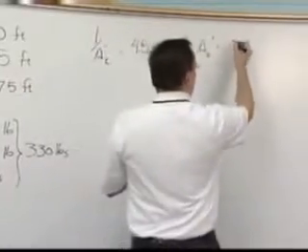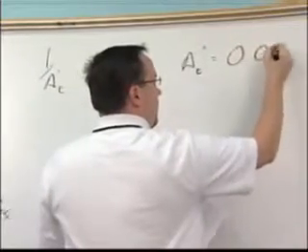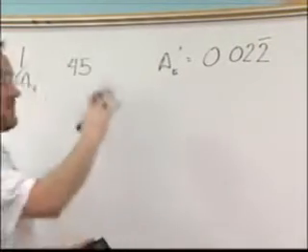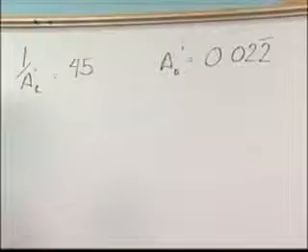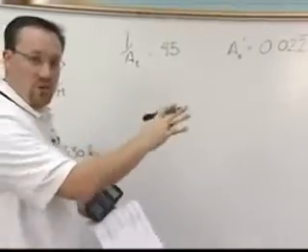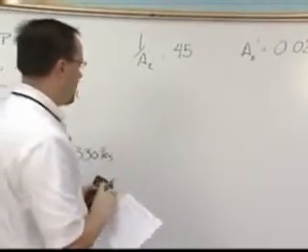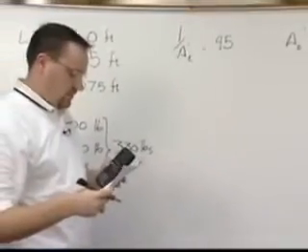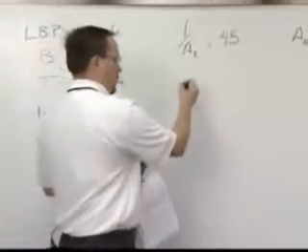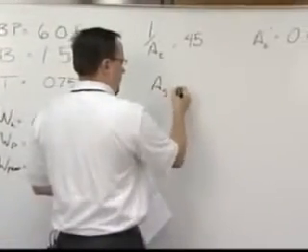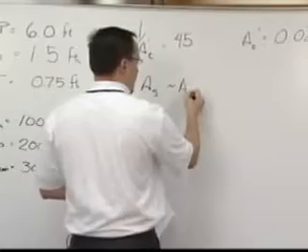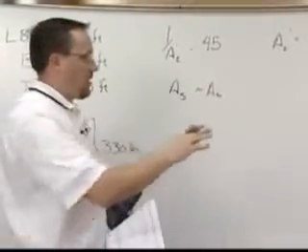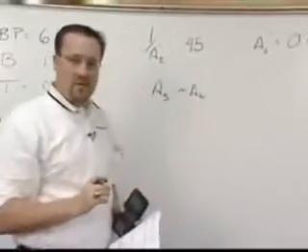is 0.022 repeat. Okay. And this is a non-dimensional unit. There are no feet squared. There's no other number or units associated with this term. Okay. In your guidelines, you'll see that there's a relationship between the area of your rudder and the non-dimensional area that comes from this nomograph. Okay. And it's dimensionalized by multiplying this number by your length squared.